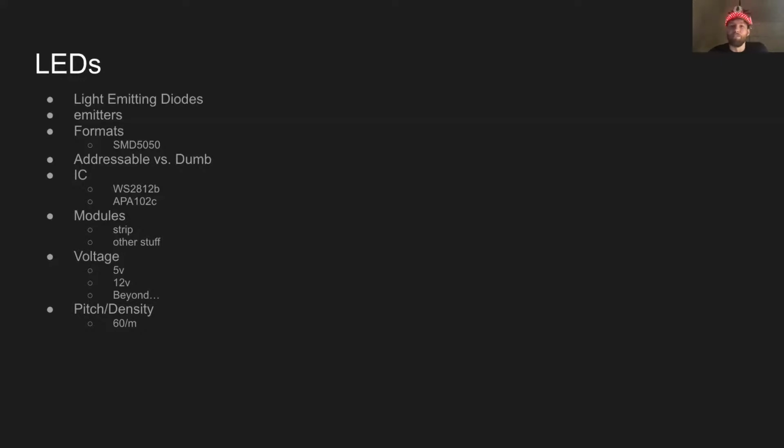But if you can pull off a well-made, robust wearable using LEDs at 144 LEDs per meter, I will be seriously impressed, and it will look spectacular. It's just a challenge. So the other option is typically 30 LEDs per meter. So that would be half the resolution that you're seeing here, much less dense, also cheaper, slightly easier to repair. So there are trade-offs here.